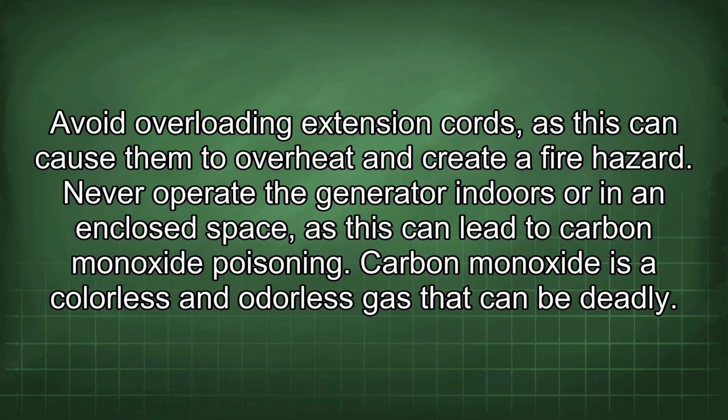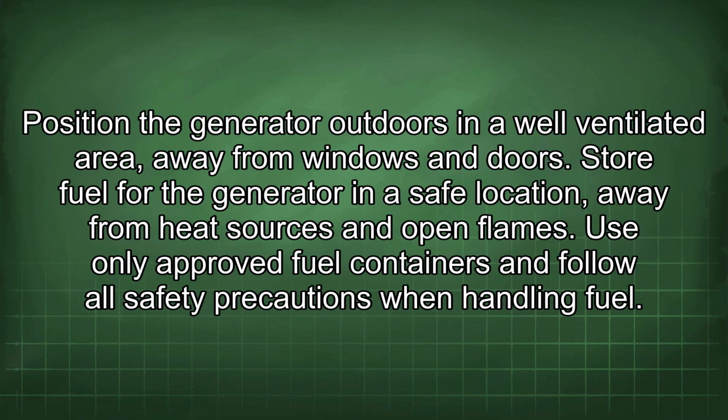Never operate the generator indoors or in an enclosed space, as this can lead to carbon monoxide poisoning. Carbon monoxide is a colorless and odorless gas that can be deadly. Position the generator outdoors in a well-ventilated area, away from windows and doors. Store fuel for the generator in a safe location, away from heat sources and open flames. Use only approved fuel containers and follow all safety precautions when handling fuel.